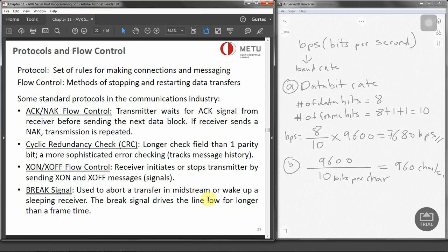So the original RS-232 connector is not compatible with standard TTL logic. If you want to use the RS-232 standard connector, we need to use a converter or a line driver, which we already said is the MAX232.